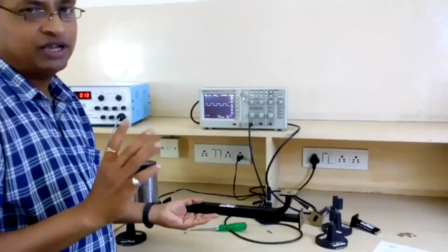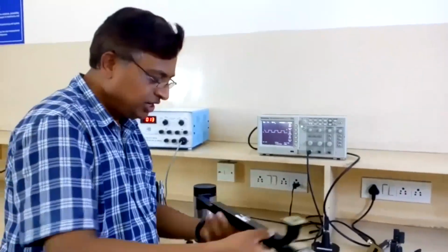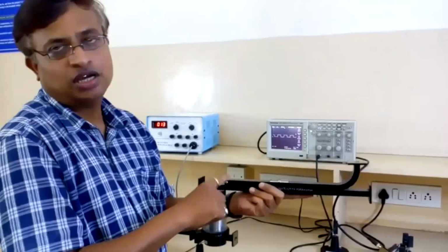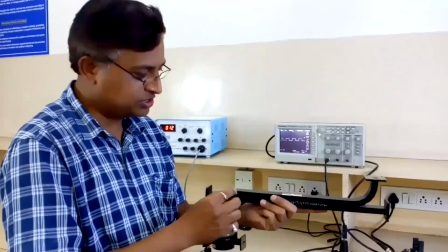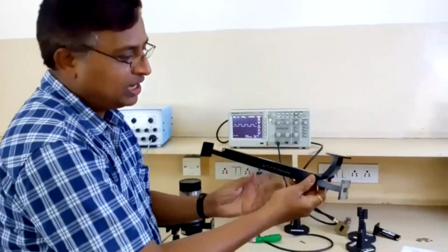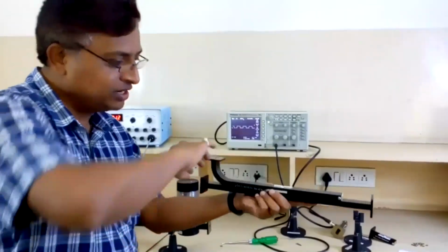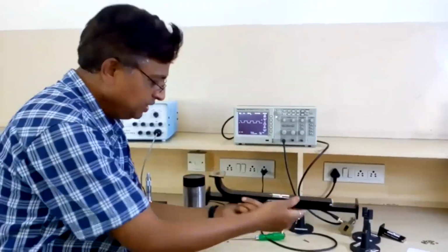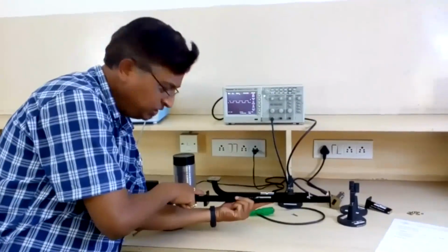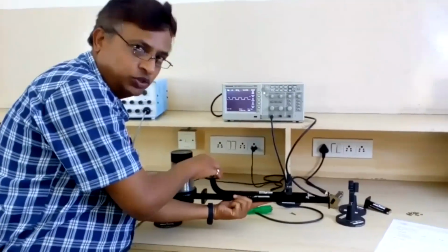To measure the third parameter, that is the back power, we cannot directly connect the signal here and measure the output at the closed port, because it is the closed port. So what we can do is apply the signal to port 2. I can reverse the direction, couple this port to the microwave bench, and then observe the output at the coupled port.